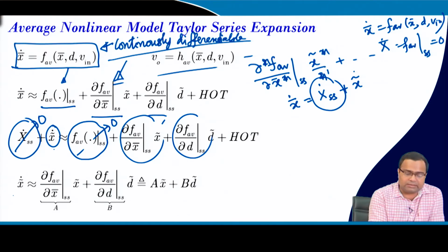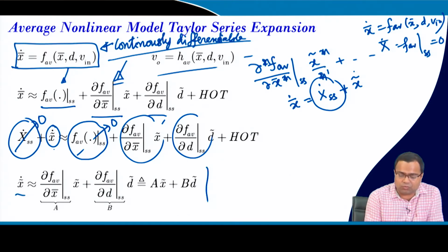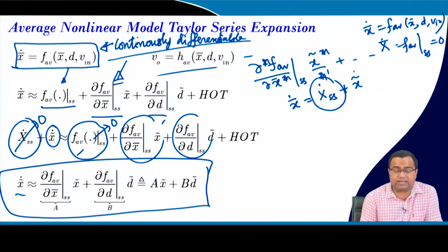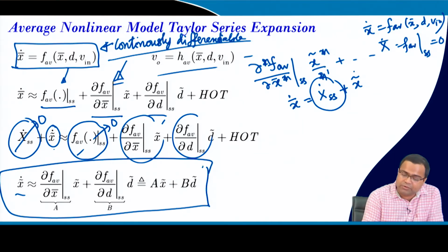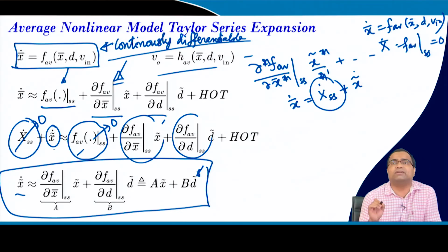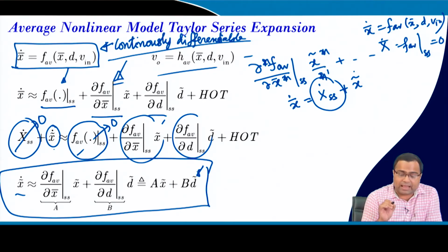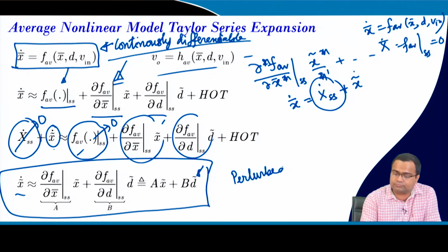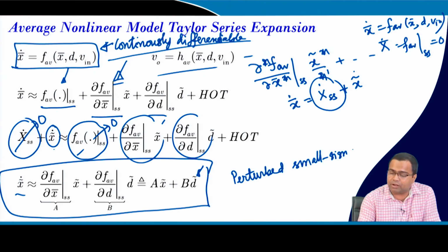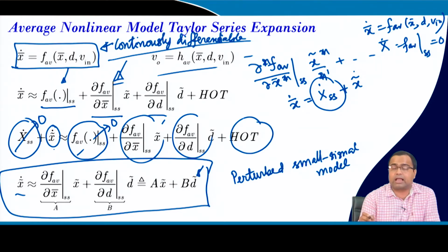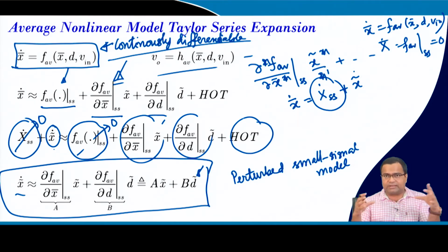of higher order terms, then this can be approximated and this will look like a linear system model x dot equal to Ax plus Bu, where u is nothing but the duty ratio, the control variable. Okay. And this is the perturbed model. Remember, perturbed, called small signal model. Why? Because we are ignoring the effect due to the higher order terms, and if you take a large signal model, large variation, these terms will come into the picture, your model will drastically deviate, and that we have discussed.